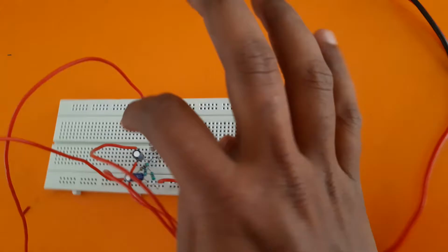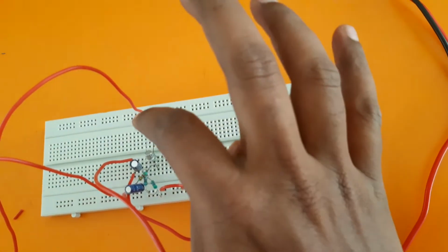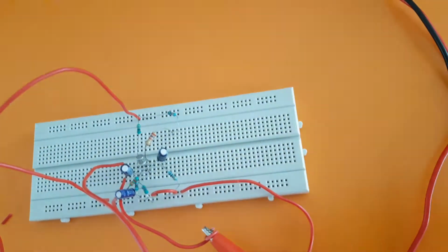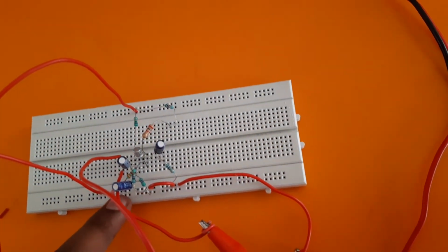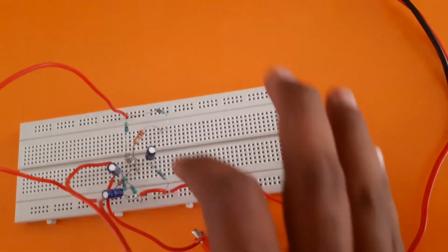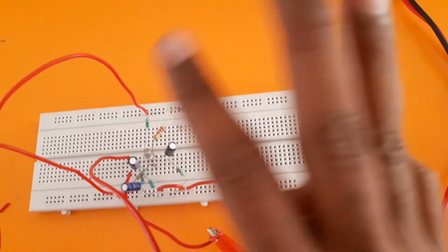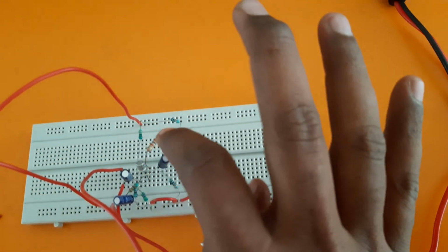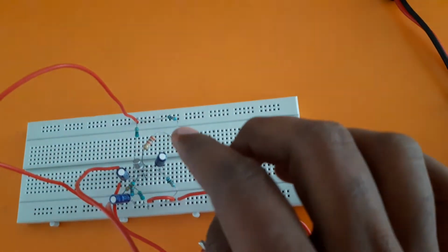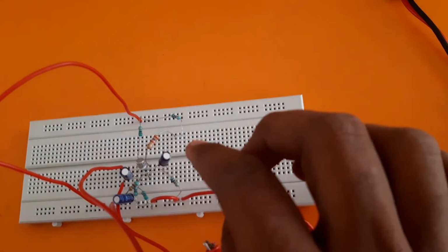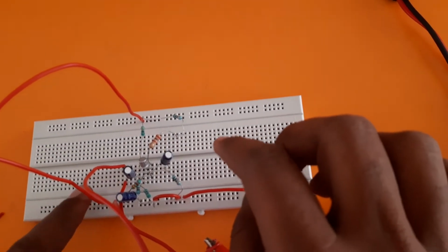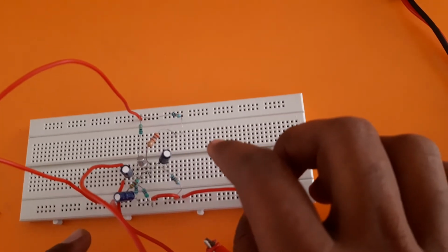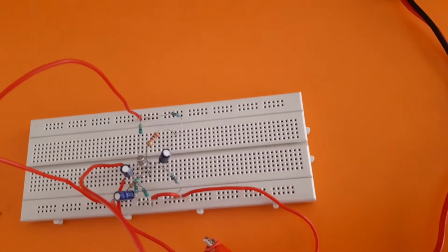Connect the circuit properly. First we give the external power supply, 12 volt here, and all grounds are connected at the last end of the breadboard, and the feedback circuit, three capacitors and the biasing voltage are properly given in the circuit. And then we give the input voltage, already set at 1 kilohertz and 1 volt, through the function generator. Now we observe the output.